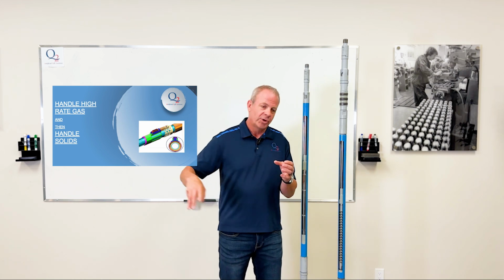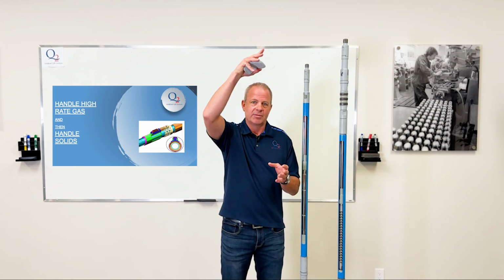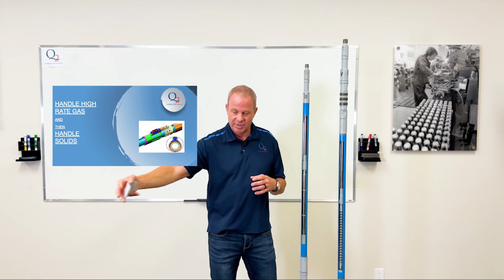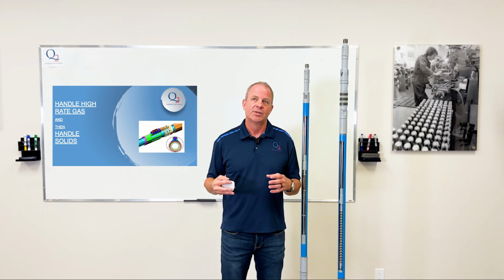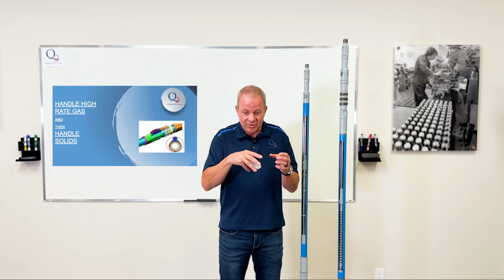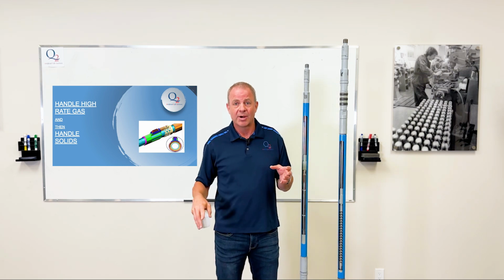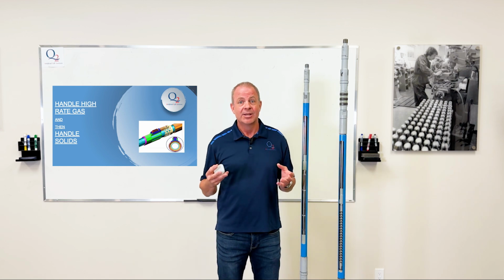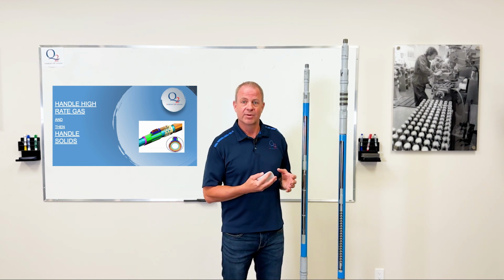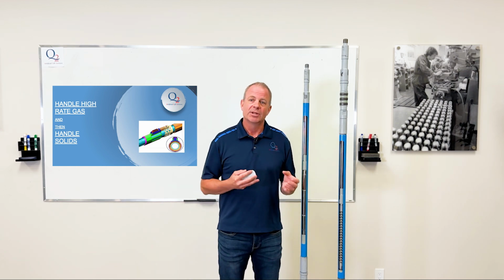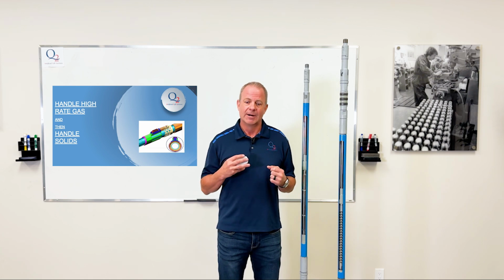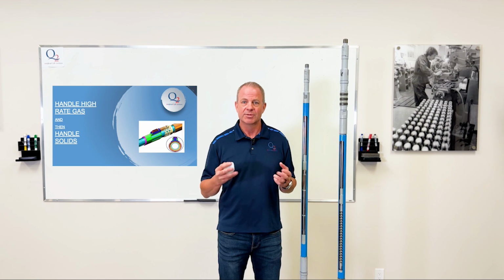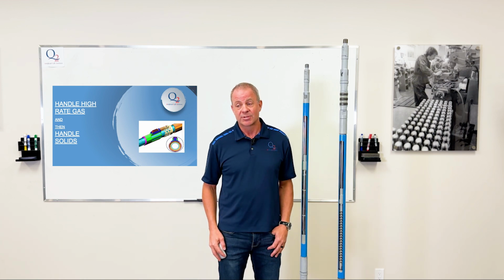So your fluid column can go all the way up the casing and tubing, thousands of feet. That comes down and acts on your pump, as well as the reservoir pressure that comes in. With the tubing, sometimes you get gas trapped below between your pump, and you're not getting the pump intake pressure that you really need to get good pump fillage. So it's interesting to look at different types of tubing anchors to give you more fluid level on your pump. That's going to help you with your solids.